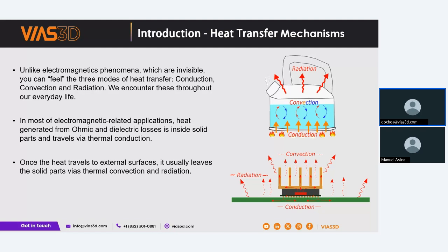So all of these three forms of heat transfer should be considered when we are doing a thermal simulation. It's very important to understand which mechanism dominates in our simulation model, because that will help us define the correct boundary conditions and even the definition of our material properties.